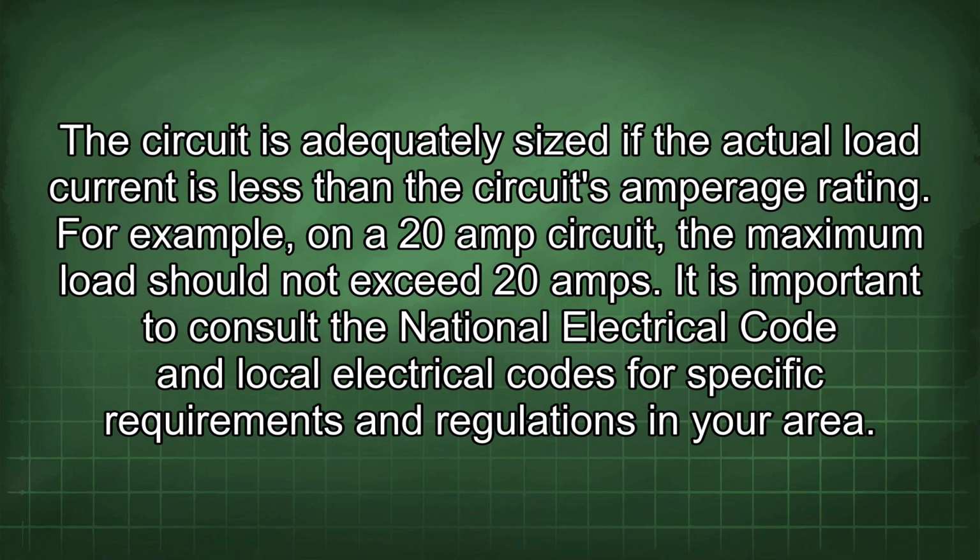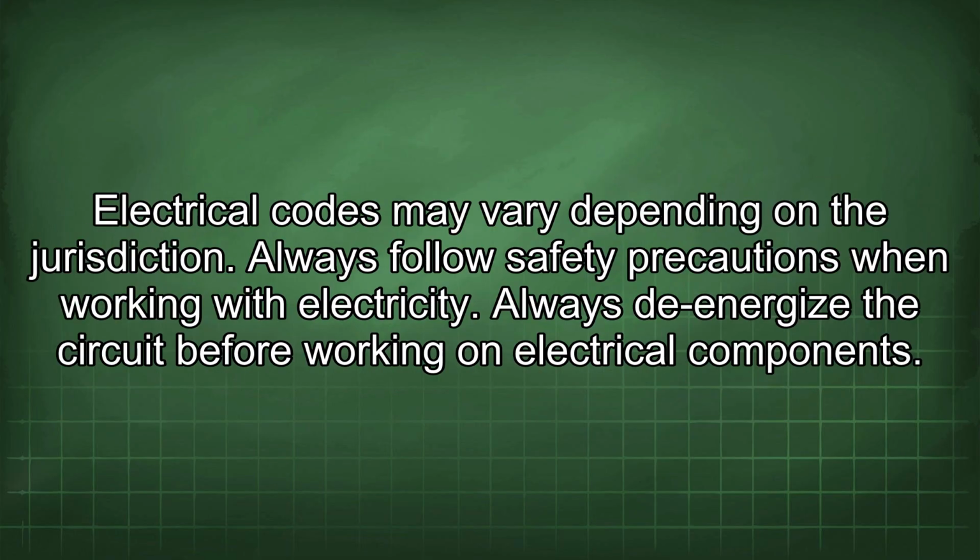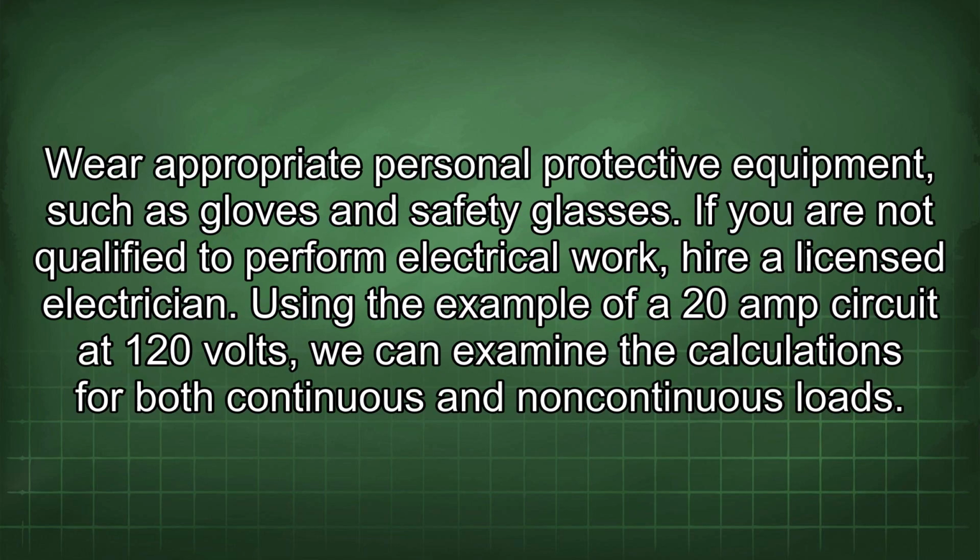It is important to consult the National Electrical Code and local electrical codes for specific requirements and regulations in your area. Electrical codes may vary depending on the jurisdiction. Always follow safety precautions when working with electricity. Always de-energize the circuit before working on electrical components. Wear appropriate personal protective equipment, such as gloves and safety glasses. If you are not qualified to perform electrical work, hire a licensed electrician.